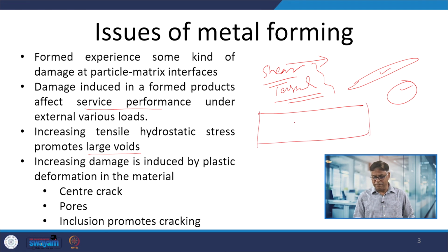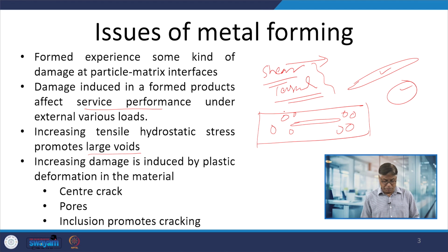This center crack may reflect at the surface, or around these second phase particles there can be void formation, also pore formation. And inclusions, especially hard, brittle, non-metallic inclusions, also promote this void formation and the related cracking.